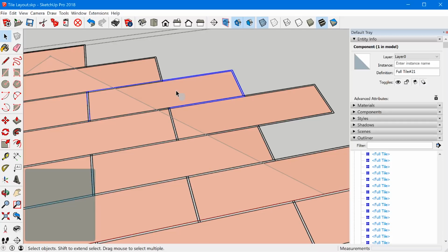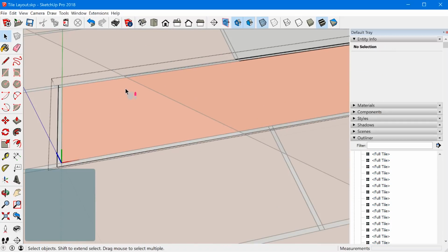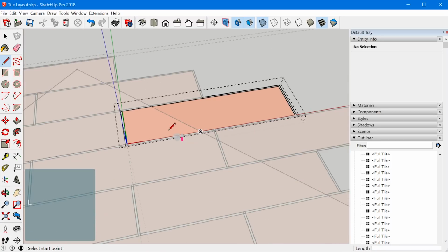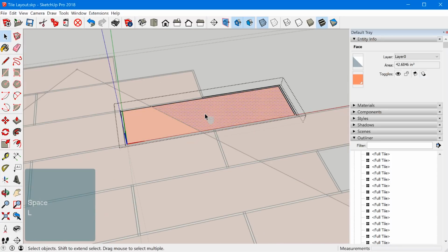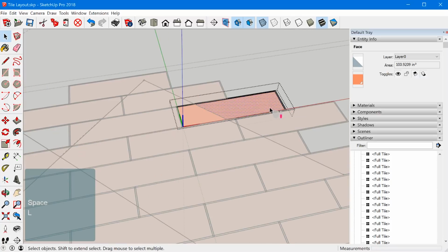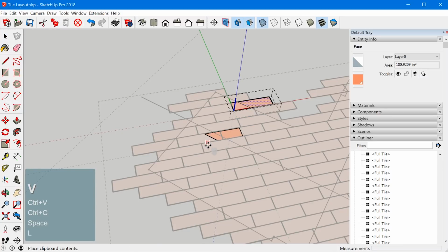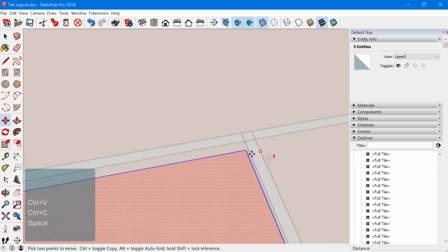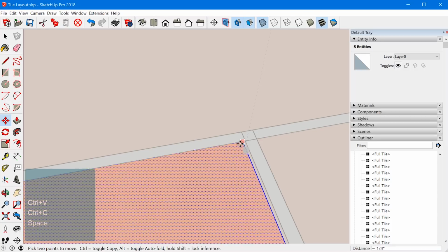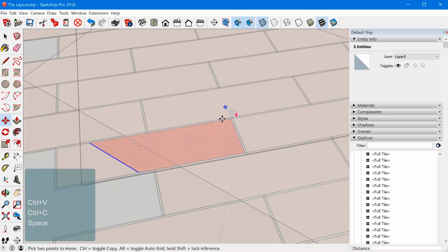And once it's unique, you jump inside, grab the line tool, and we're going to just divide this face where the wall intersects. So now you can select the cutoff piece and press Control C to copy and Control V to attach it to your mouse cursor. And then you can just go through the model and find a nice piece that you want to replace with this piece. And then you can just fine tune the position and lock it in place.